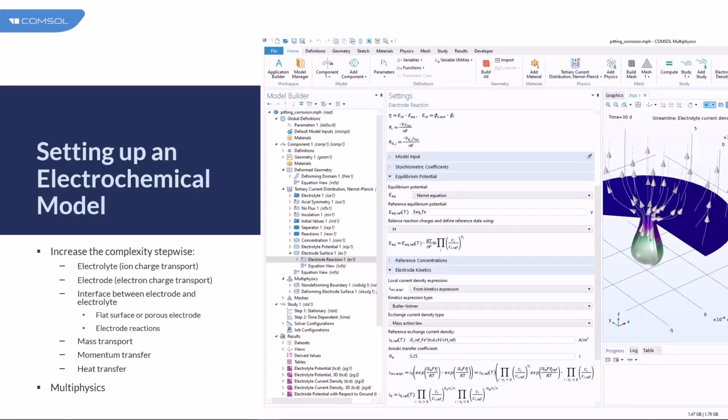If the conductivity of the electrodes is much larger than the electrolyte, you might not need to consider the potential drop inside the electrode, and you can rather represent them with a constant potential boundary condition. For models with porous electrodes, or for example long pipelines, the potential drop inside the electrode must be considered, because it affects the polarization of the structure.